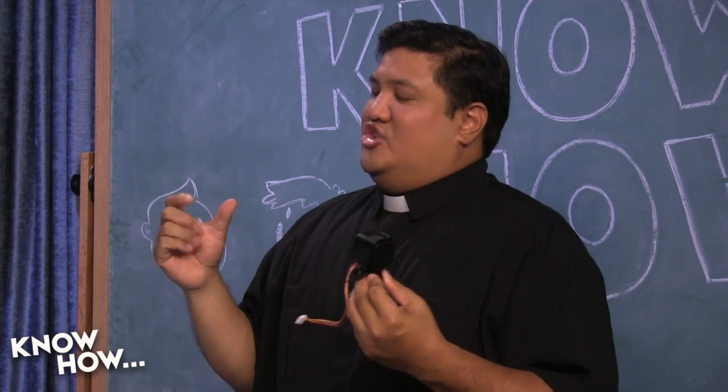Yeah, and this is actually something you want to do with your 3D design because it's very easy to be so convinced by the strength of the material that you're like, yeah, I'll just put a screw through there and the plastic will hold it. Right. Always think about what you could do to reinforce it. And if I can make the collar a bit more snug, a bit more solid, I'll do it every time. Or avoid using hot glue or something like that. Yeah, do that.